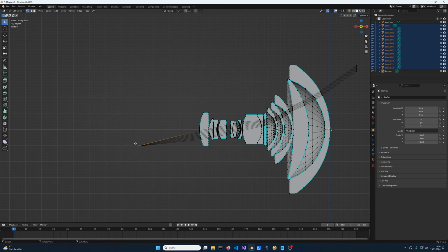We can double check this calculation forward by now looking at the vertex position. So I'll just pick one of the vertices in the focus spot here, and we get a Z coordinate of 10.4. And we would expect 10.8, which is half of the 21.6. However, when the lens has some distortion, as you can expect for any real lens, you would also expect a deviation from this f-tan-theta relationship, and this is exactly what is happening here.